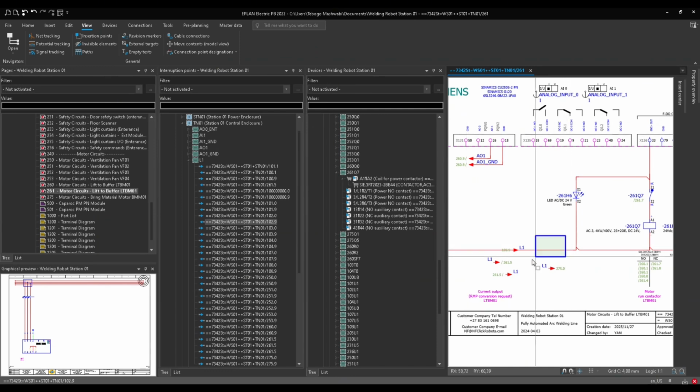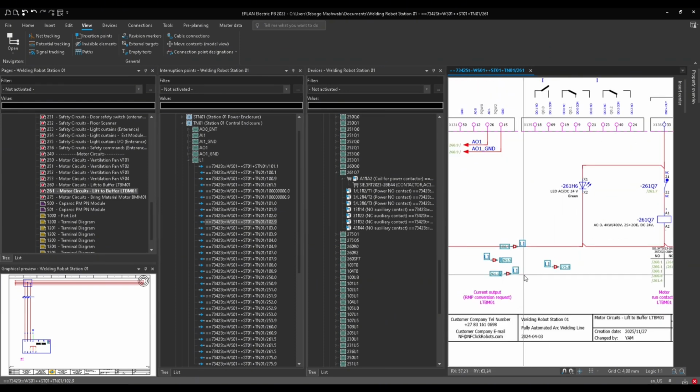The only problem, yes, indeed, which I will get is that maybe I'm missing a head, or maybe I'm missing a tail, or maybe this one does not have an electrical connection. So you can see this one does not have electrical connections. So these ones here, they do not have any electrical connection. Only this one has. So therefore, I'll actually get an error inside EPLAN for those ones.